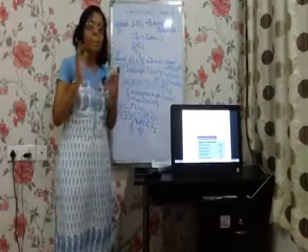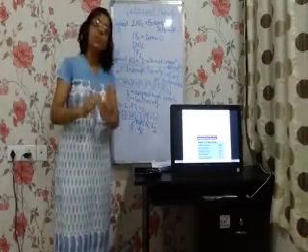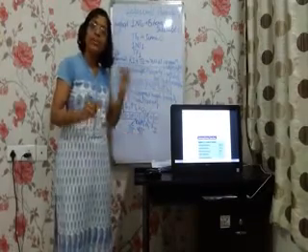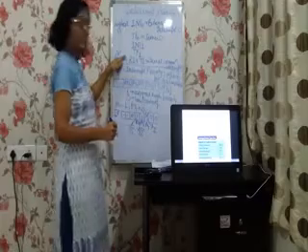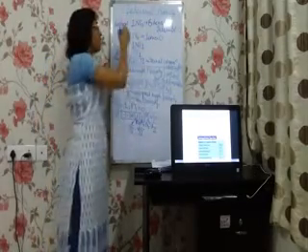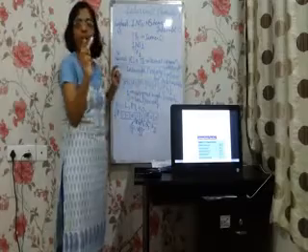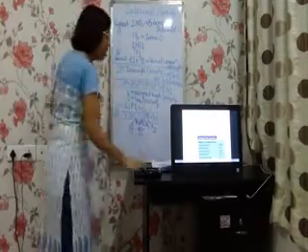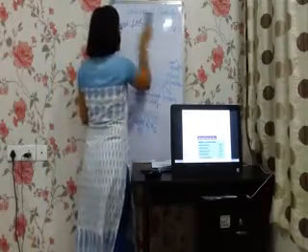But if more than 1 bit of the IP register is 1, then the 8051 will refer to the standard table that we have already drawn here. Out of those multiple ones, according to the table, the 8051 will assign the final priority and serve the interrupts in that manner. This is interrupt priority.